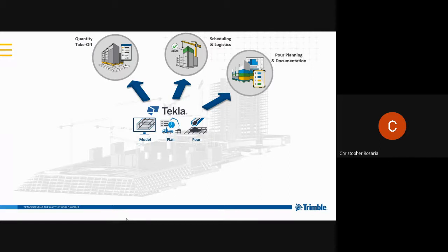So we also do pour planning and documentation. You can establish pours using the unique pour solution. All these are going to be shown later. So joining objects with, for example, the same concrete mix, and then breaking pours using our pour break tools. And you can actually communicate that pour graphically. So you'll see color-coded models that tell you whether the concrete has been poured, what's the status, is it ongoing, or it's finished.